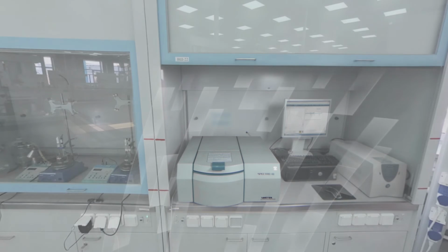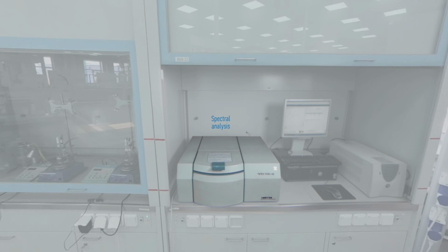The spectral analysis is performed during quality inspection of the ready oils and additives. It allows the determining of chemical composition of a sample. This is a sort of prompt analysis to control the proportions of components and additives at oil manufacture. This analysis is also used to determine the authenticity of products in disputable situations. The set of additives in oil is like a fingerprint. It is individual for every oil. Thanks to the spectral analysis, one can assess the content of metals and other components in the oil.